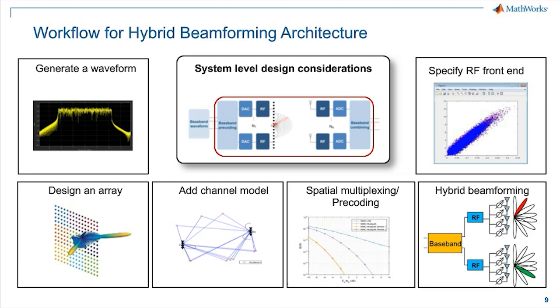You can either create a baseband signal, an RF signal, and actually using RF instruments and software-defined radios transmit over the air, or you can model all the imperfections and distortions that the channel adds to a digital and analog signal. And we have lots of channel modeling which takes care of that for you. As I mentioned, if you know the nature of the channel, we can use that to design precoders and combiners as essentially matrix operators that map different segments of the beamforming sections one after another, and you can apply this spatial multiplexing approach to the MIMO OFDM system that's 5G like that.